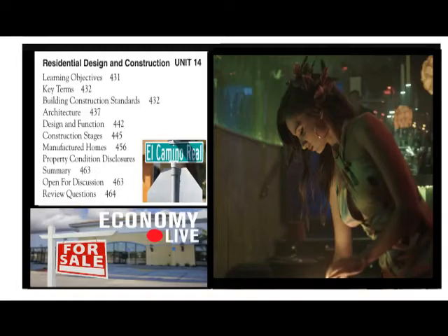The solution to a high level of radon is to add ventilation to the area of the building closest to ground level, such as the crawl space, to vent the gas and prevent it from accumulating to a dangerously high level. Information on radon and mitigation measures can be found at www.epa.gov.